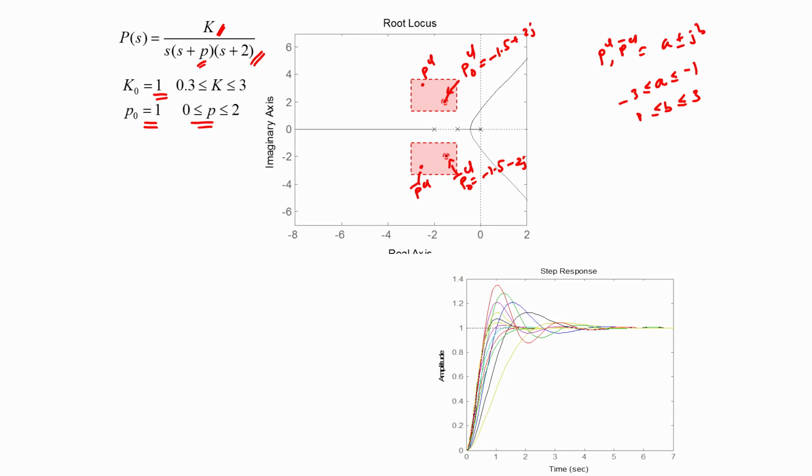So what we are essentially saying is that as control engineers we are okay with the closed loop system having such a relatively large spread in its response, because this is acceptable for our particular application, and if we permit for this large a spread in the response, we are essentially therefore also indirectly saying that we are okay with the closed loop pole wandering over a fairly large area in the complex plane, and in this particular case this area is bounded by the rectangle that we just talked about.